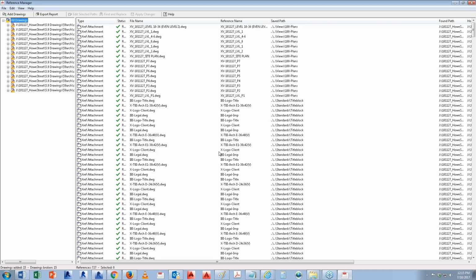The reason why we do not want to use full path is because, let's say the project gets archived, your server will want to pick up whatever's the last project, and most of the time the object will get lost, and you have to repath all of that stuff when you have to recover a lot of these files.